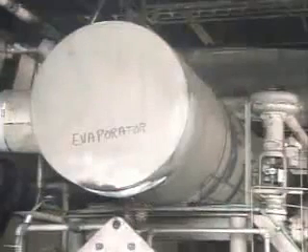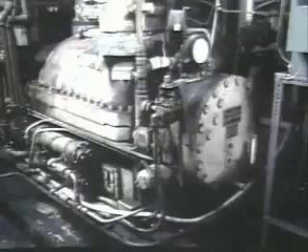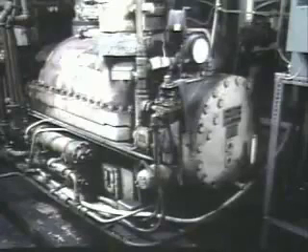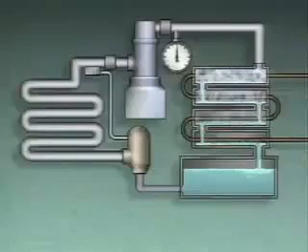Now, a refrigerant flow rate that is too high can also occur. If the expansion valve sticks too far open, there may be too much refrigerant in the evaporator. This could cause the evaporator pressure to increase. In systems that cycle the compressor on and off, the compressor could operate continuously. This is because pressure in the evaporator is higher than the set point for shutting off the compressor.